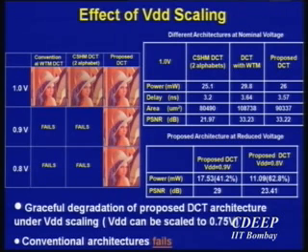Fail meaning, if the DC component fails, it's going to be a really bad image. So you're not meeting your PSNR, or peak signal to noise ratio. Everything is determined here in terms of the peak signal to noise ratio. The original image was about 35 dB or so. And in this one, certain computations are not done. The way to compute it is that you look at the original image and the image that you receive, and you can do a mean squared error, or you can do other kinds of SNRs. So this one is about 23 dB versus this one at 29 dB and so on. And the original one is about 35 or 33 dB or something of that sort.